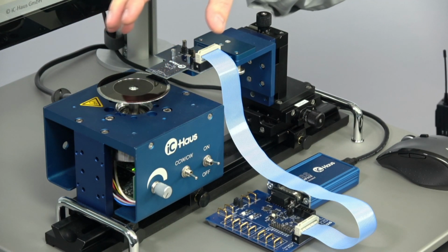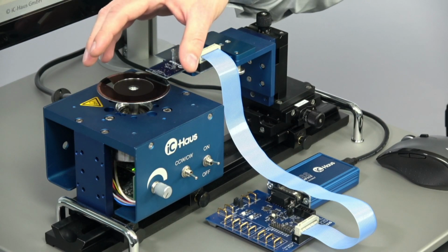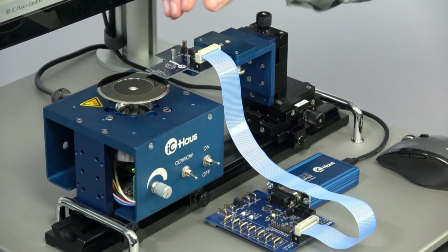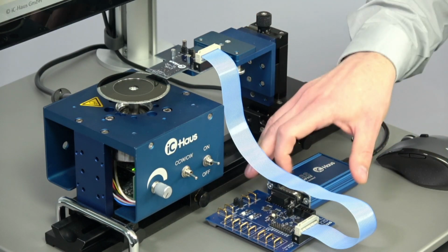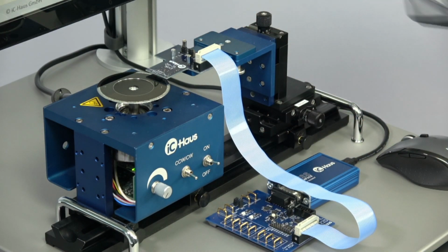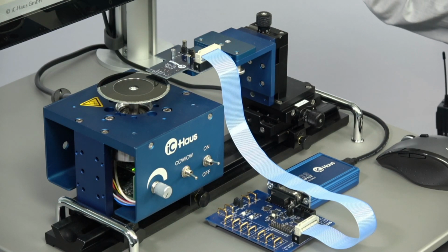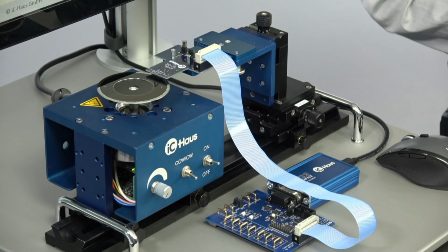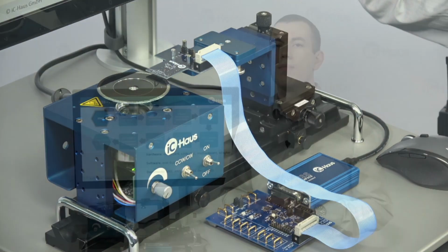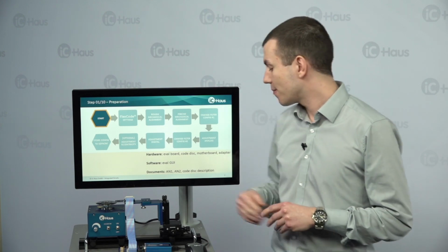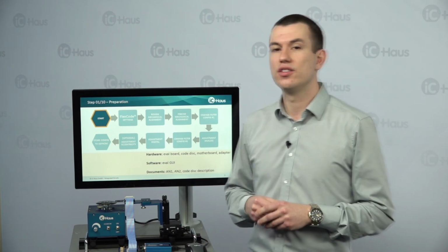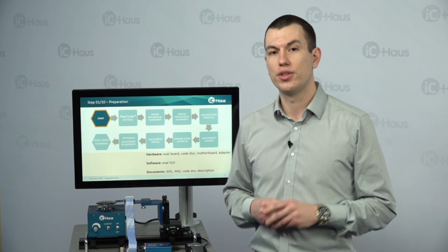And next to it, we do have our 69mm aluminum disc, the PZ05SM, that is sitting here. And via this ribbon cable, I've connected the PZ2D, which is our motherboard, that allows for somewhat easy signal inspection and also a very comfortable connecting of the components. And to the sub-D connector of the PZ2D, I've connected one of our base to USB adapters. I'm using the MB5U here, but you're of course free to use the MB4U or also MB3U, it doesn't matter. And then I'm going via USB into one of the USB ports of the computer.